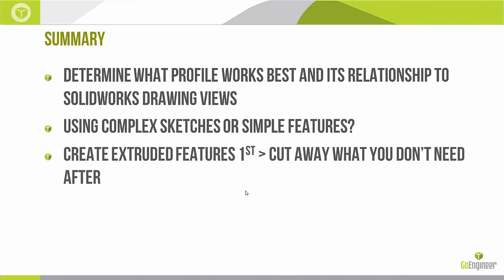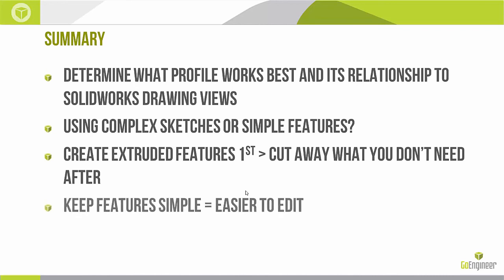This rule right here always works best for me. Create extruded features first, meaning that you're creating material, and then after that just cut away what you don't need. And of course, last but not least, it's kind of a rule in life that I like to use. Keep your features simple. They're just a lot easier to edit.